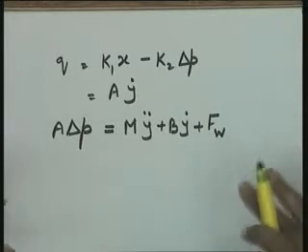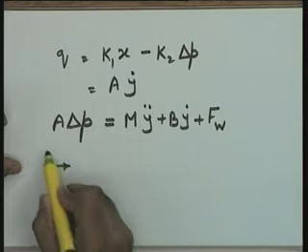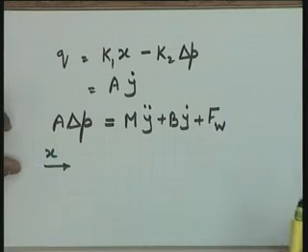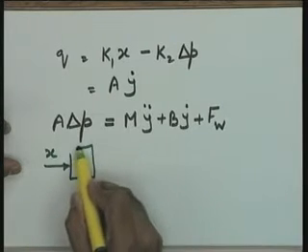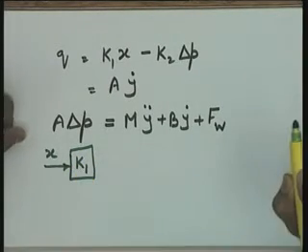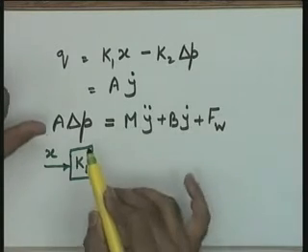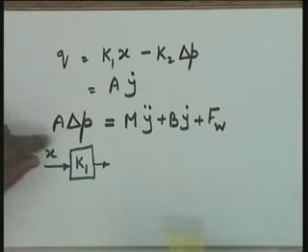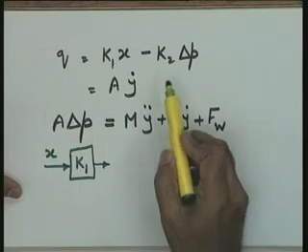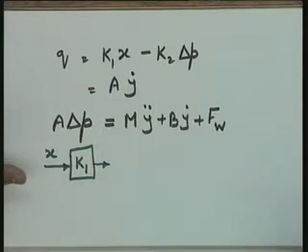So in this case, if I use this very space so that these equations are available with me, I start with the input variable straight away. So the input variable is x. Look at this point. I am multiplying this by k1, so I get k1 into x. To generate del p, you see I want to generate del p. So help me, how do I generate del p? Through the block diagram I will put it this way. I know that K2 into del P is equal to K1 into X minus A y dot.